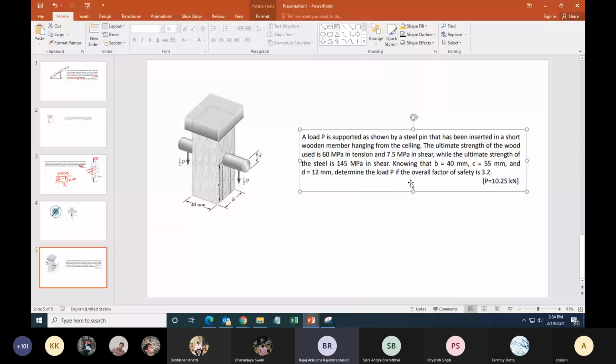So the area parallel to the ceiling, let us call it like this. It could be, number 3, double shear in the pin. Dislodge of wood from the top surface, and that a bearing. No, wait, the dislodging is not given. It is said that it is stuck properly, hanging from the ceiling, and that glue is not going to fail. But below it can be so.